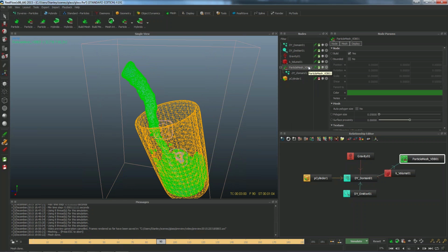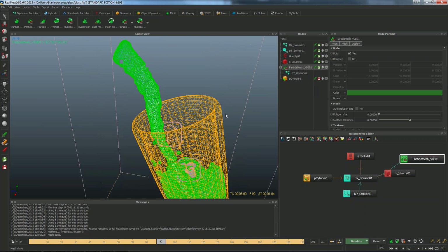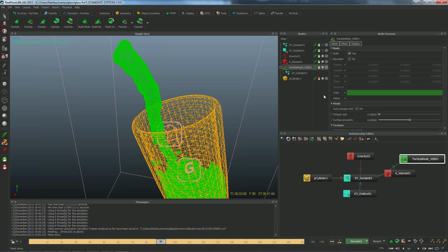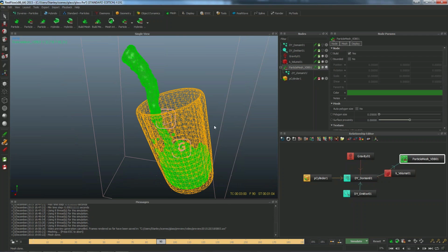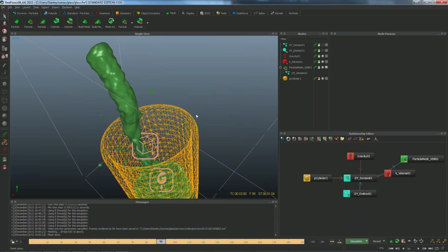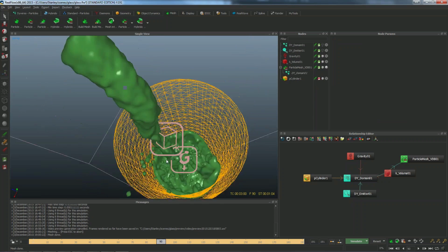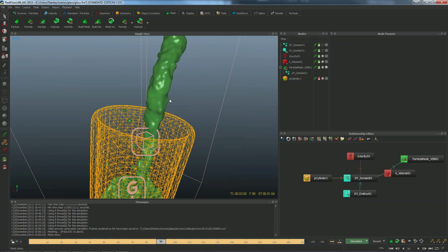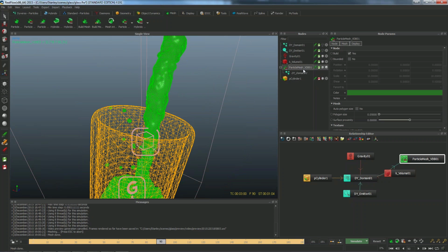Let me perform a couple of actions here. First of all, in order to take a better look at the mesh, I'm going to hide the particles themselves and set up the mesh as a smooth shaded object here, okay? So you can see this kind of blobby aspect here, which is not really realistic, right? We probably should try to smooth the surface of this mesh, and there are some different ways to achieve that